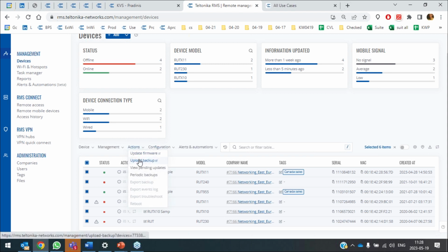What you can do with that, first, it's important that you can do a firmware update. Connect all the devices here, run the firmware updates, and make sure all the products are up to date, so you will not have any problems using any operator SIM or some sort of configuration that might be wrong with the old firmware. It's good due diligence, so when you get the devices, just run the new firmware to make sure it's going to work well.